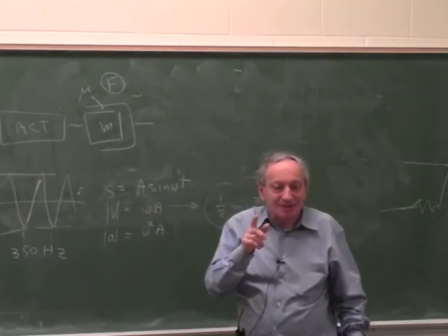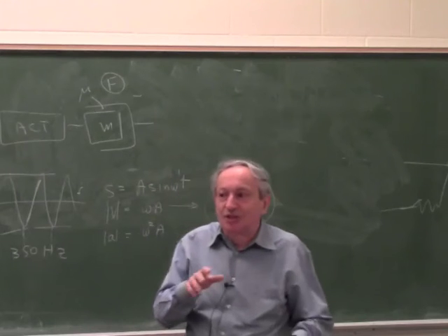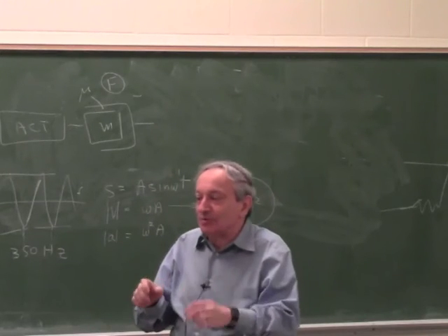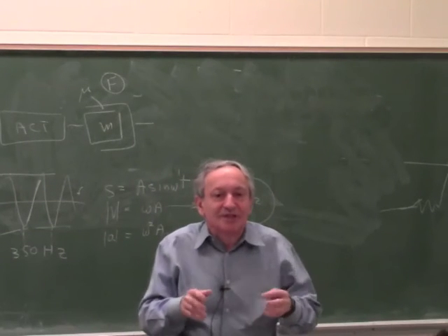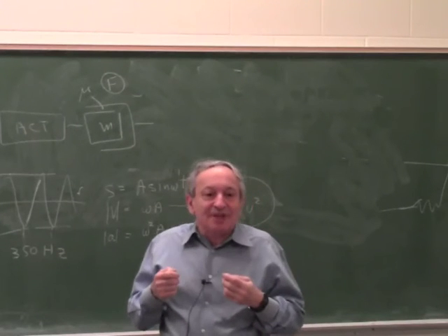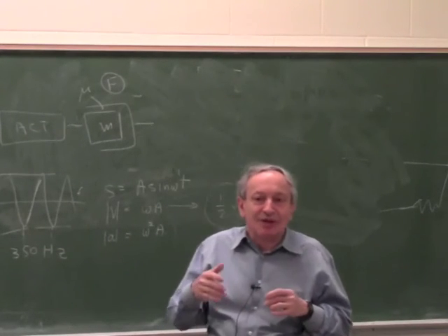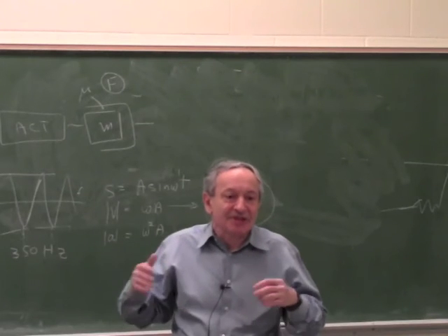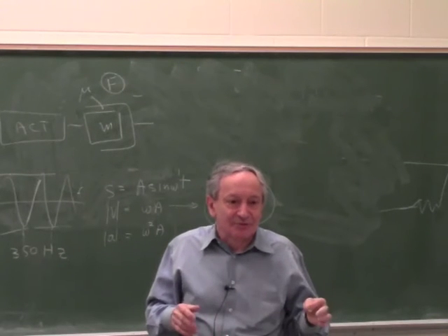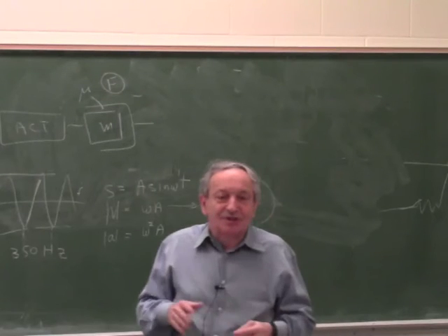Regenerative, not just dynamic. I mentioned to you the difference between dynamic and regenerative. Dynamic is just you apply some power to the motor to stop it. Regenerative, you actually take the energy back from the actuator. So strangely enough, all the inertial forces which cause power is fully recoverable. Now, in reality, it's 90% recoverable, because when you make the actuator into a generator, the efficiency is not 100%, say 90.